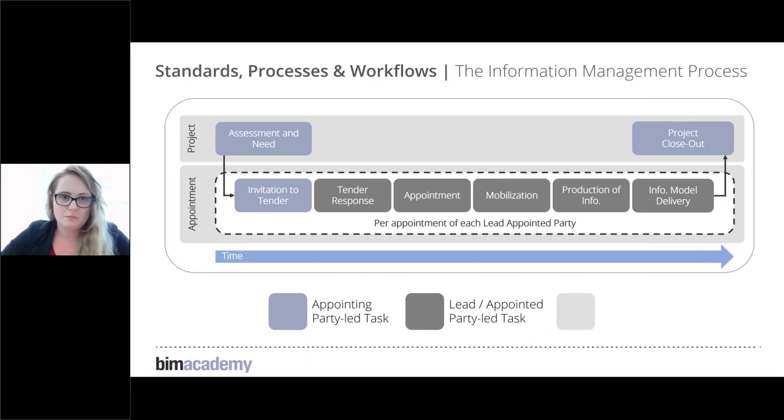This relatively complicated diagram sets out the workflow, in particular in ISO 19650 Part 2. And without going into too much detail, and I've just realised there's a blank box in my key, it sets out how the client defines their information requirements, goes out to tender to appoint those that are able to meet those requirements, at which point there's a mobilisation period in order to fill any gaps in the appointment.